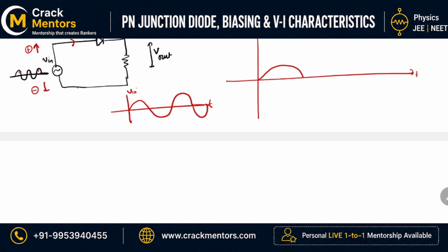But as soon as the voltage switches its sign, it changes its direction and goes in the reverse direction, the current will start going like this, and it will find that it is a reverse bias condition, I cannot flow here, therefore the current output becomes constant. For the next wave which is in positive direction, it will be again like this. Next one it is like this. Again it is like this, and in this way the voltage output keeps on changing.